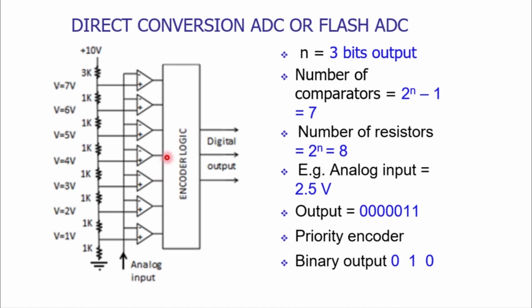Here as well the output is 1, because 6.8 is more than 4 volts. Here again the output would be 1. Here as well we are getting the output equal to 1. But at this juncture we are not getting any output, it would be 0. So D1, D2, D3, D4, D5 and D6. So here the sixth comparator is giving the high level output, that is 1.